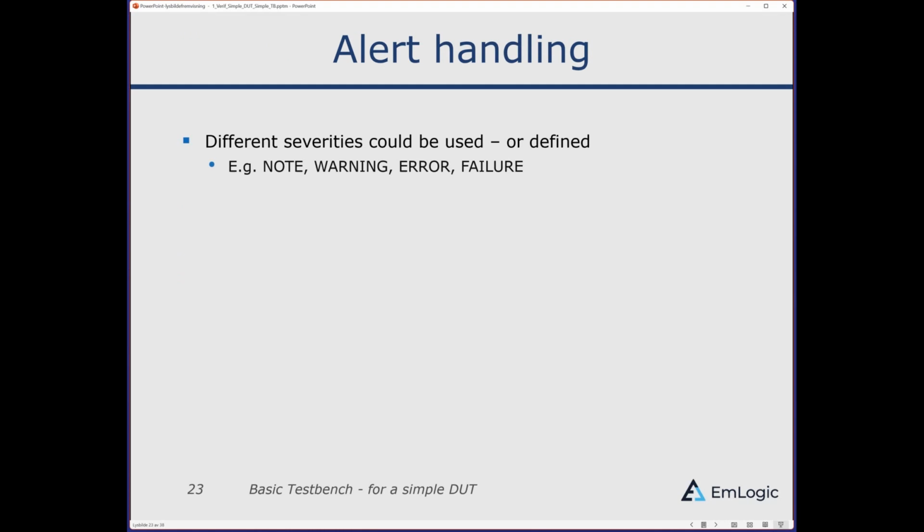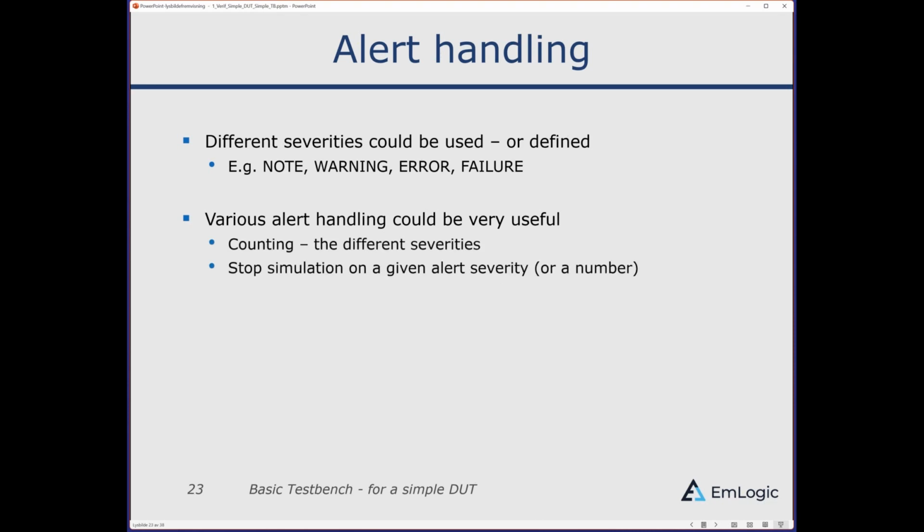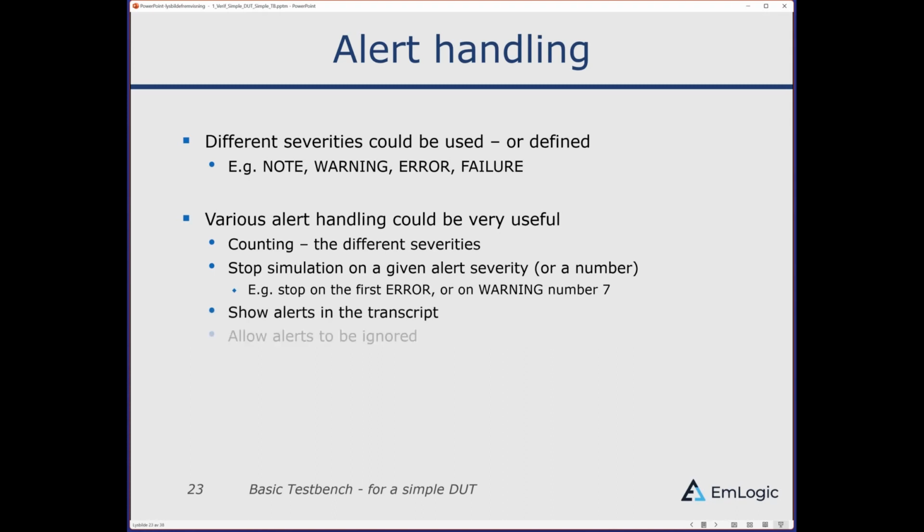So you might say that verbosity control is not really required for really simple test benches. And that's true, but I would say it provides an advantage even for really simple test benches. And I think it's more efficient to use the same methodology for any type of test bench, whether it's simple or really advanced. And also it's a tendency that most test benches tend to end up more advanced than you originally assumed. And of course, if you use some kind of methodology, a library, whatever, that provides this functionality, it doesn't really give you any overhead in your verification development or test bench development.